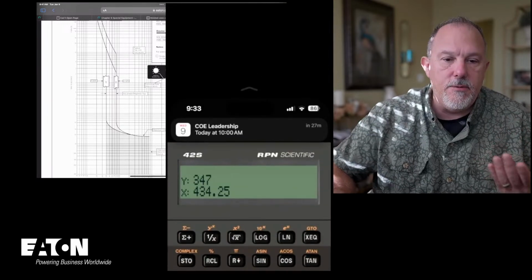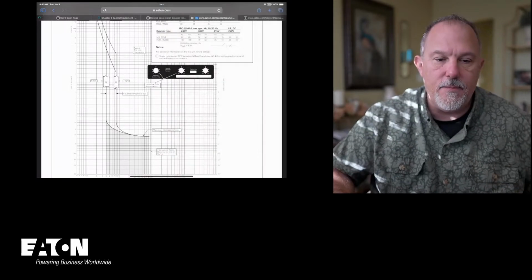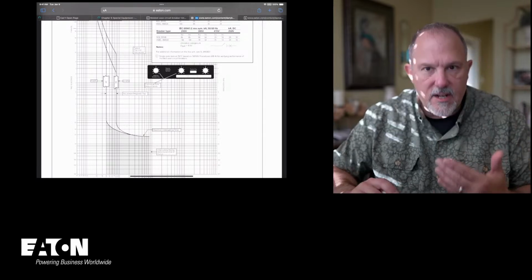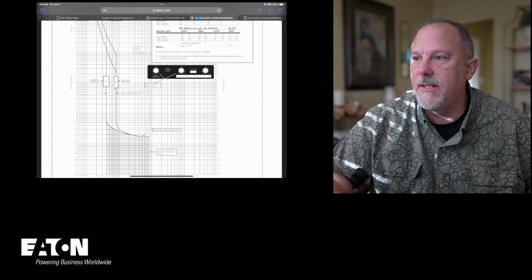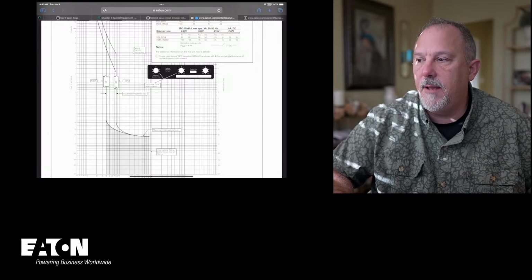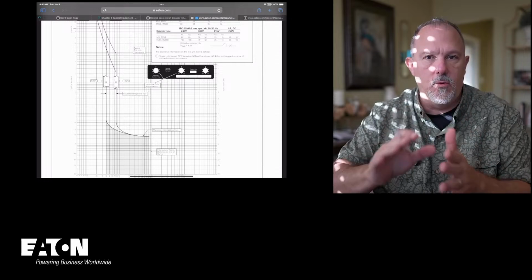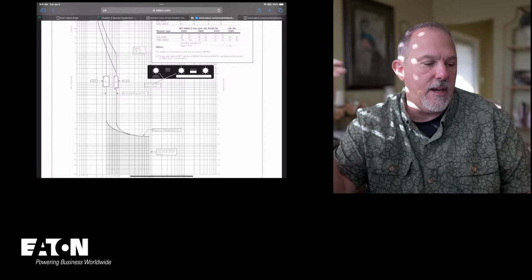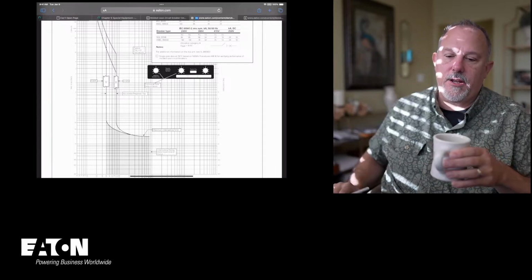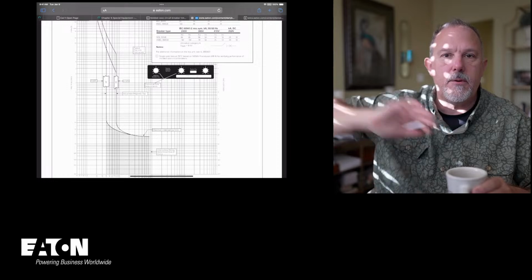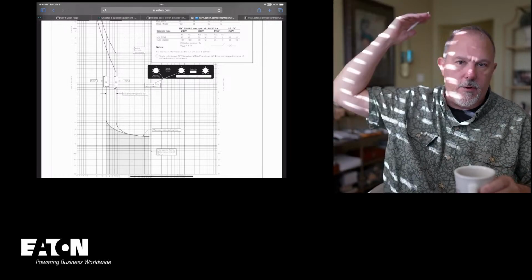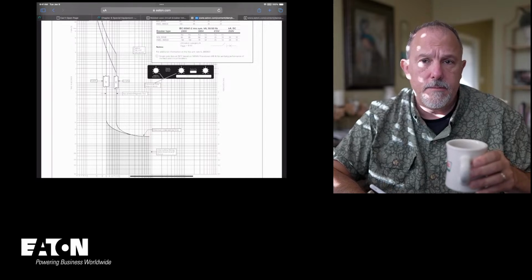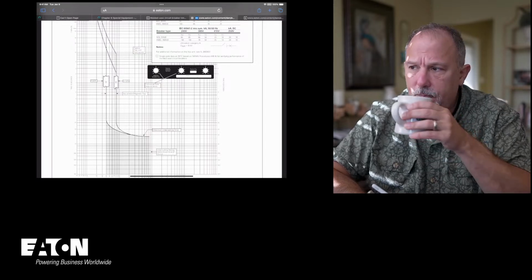But what I'm going to do now there is instead of putting in 10 or 15 seconds, I'm going to put a clearing time of 2 seconds. That's that 2-second rule that we get from IEEE 1584. And what is that assumption? That assumes that, you know what, the energy is going to be so much, you're going to be laying on the ground, the energy is going over top of you, or something so bad has happened at that point, you're not in the picture after 2 seconds.